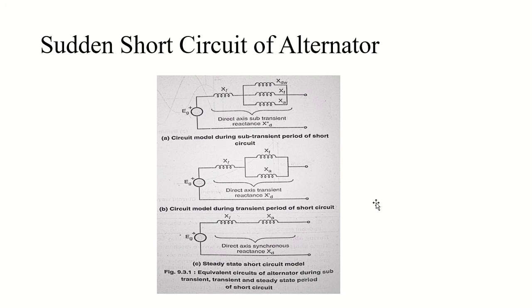Now this sudden increase in the armature current will produce armature reaction. The air gap flux will not be able to change instantaneously and the armature reaction will oppose the main excitation. Now, in order to counter this whole situation, the demagnetization current will appear in the field winding and damper winding as well, which will help the main flux.